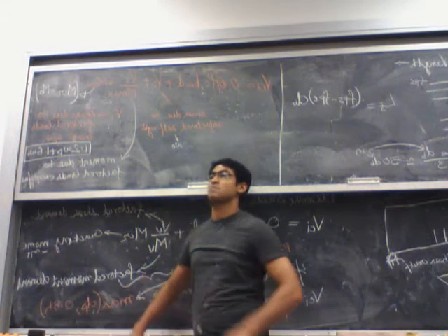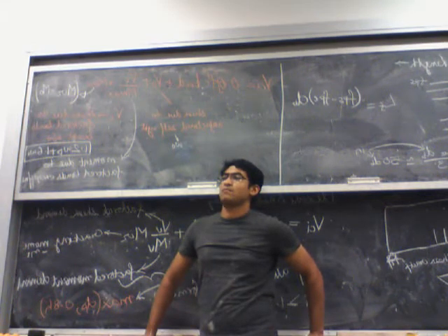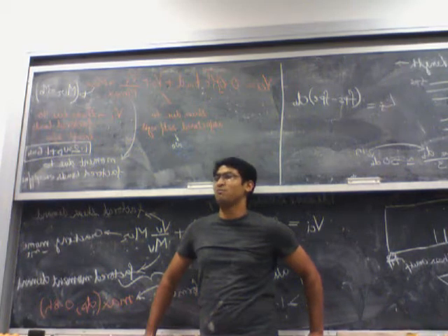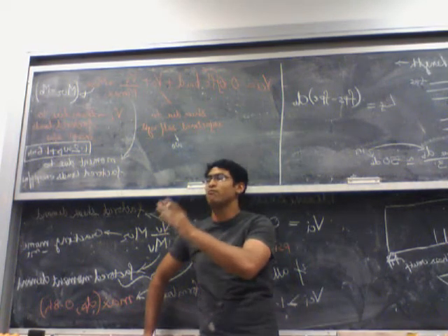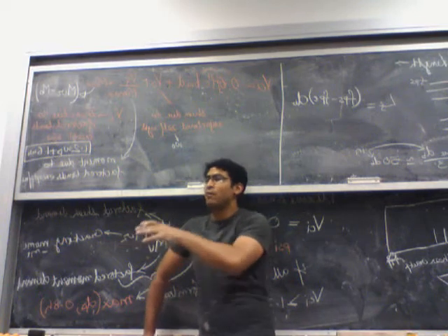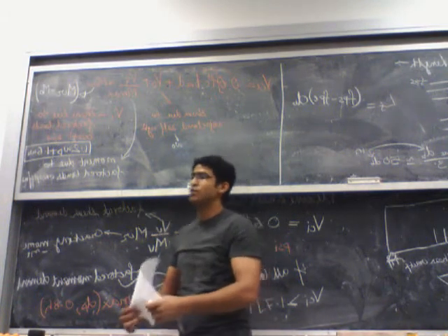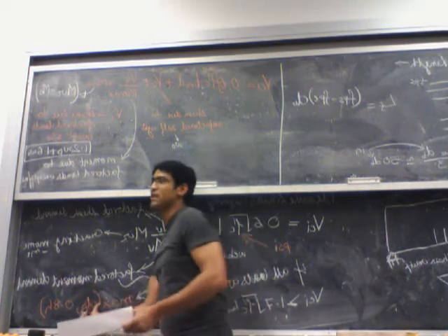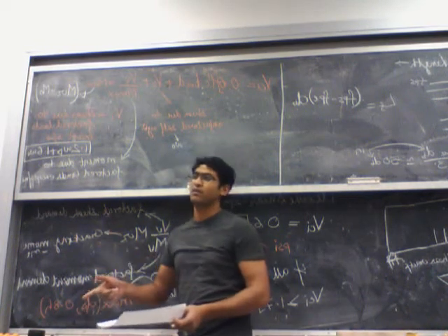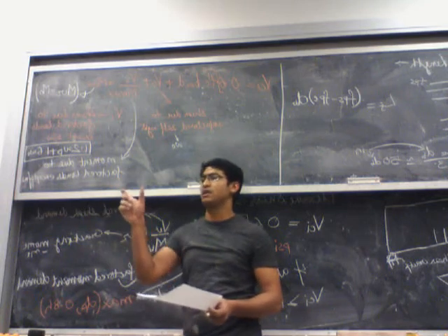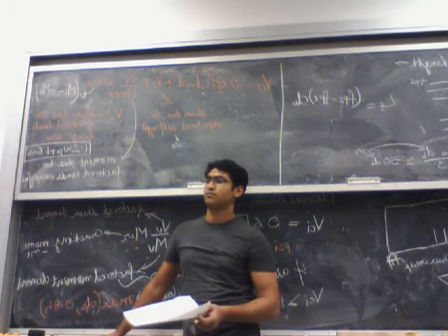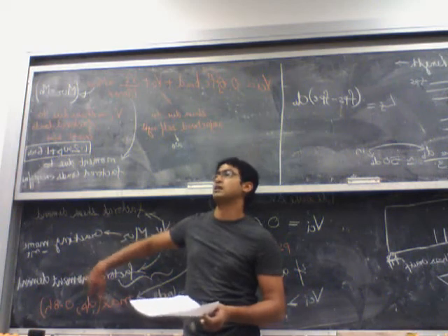It seems like there are cases where on one side they want dp only to the pre-stressing steel. Yep. But it's not really clear. No, it is clear if you look into the fine print. Since we keep using the same name for all centroids, in some formulas, if you are just using the centroid of the pre-stressing steel, they'll still use dp. Like in the shear formula, it's to the centroid of all the steel. They use the same convention, dp. That's why it's confusing. If you look into the text, it will say clearly whether it's just to the centroid of the pre-stressing steel or to the centroid of all the steel. But in this case, for shear design, this dp is to the centroid of all the steel.